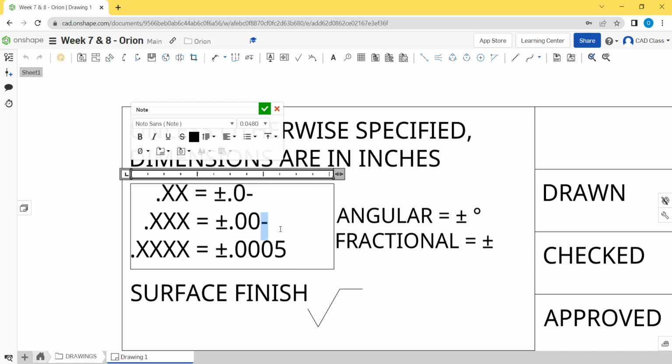0.003, we'll do plus or minus 3 thou, or 5 plus or minus 5 thou, somewhere in that range. This is pretty common for a 3-digit precision on an inch drawing. You'll see these vary. And then, 2 digits of precision, we'll say this is plus or minus 0.01, I believe, is a little more common.